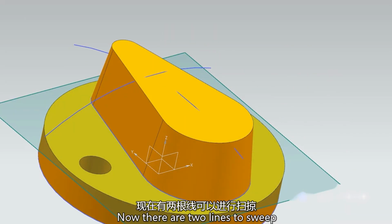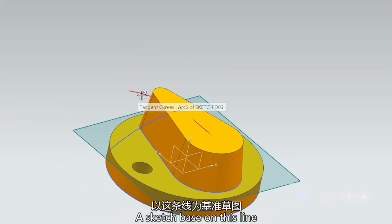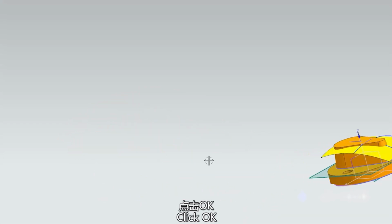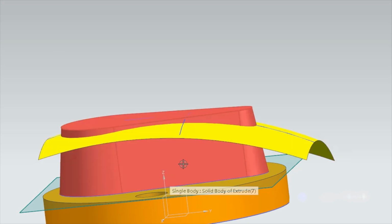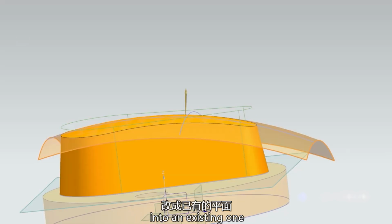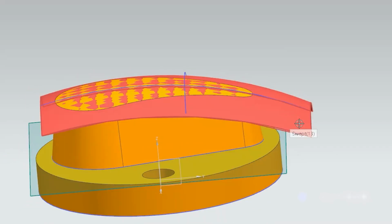Now there are two lines to sweep. A sketch based on this line. Then draw a surface with this line as the guideline. Click OK. Then trim it. Trimming body. The entity to be trimmed is this graph. Then you have to choose this face to change this new plane into an existing one. Then click OK. So this has been trimmed.